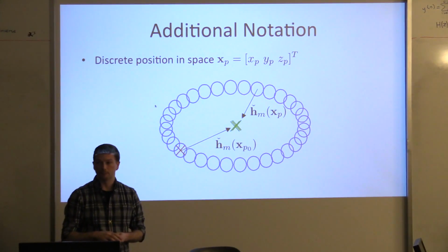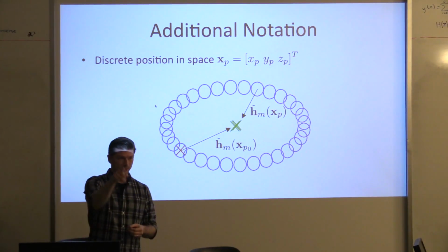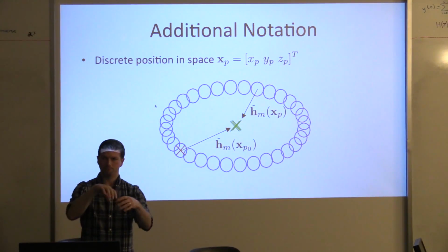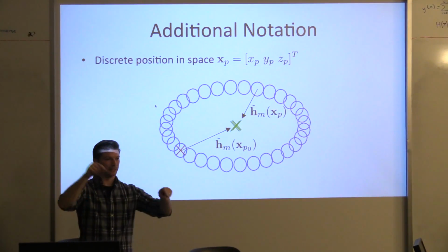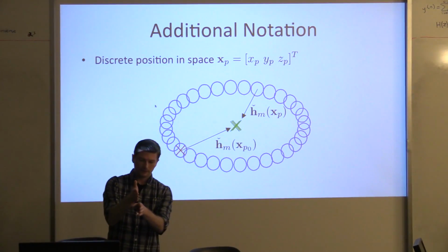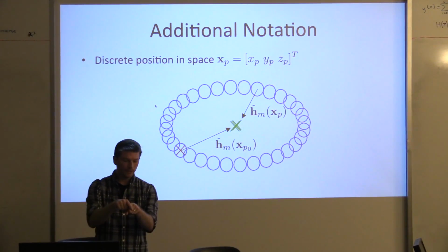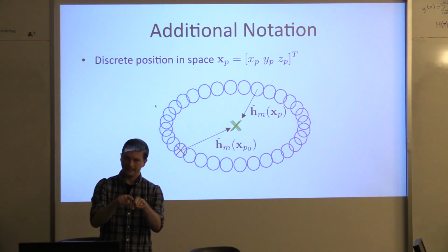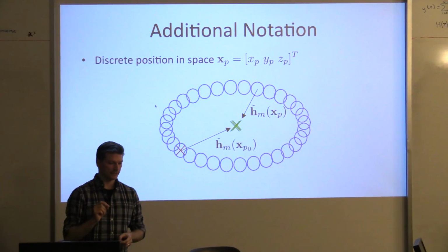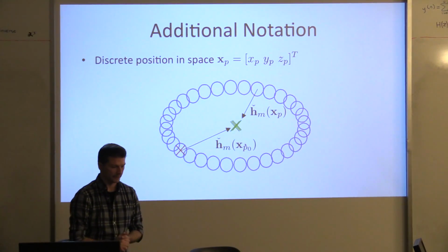So if we're going to design a practical beamformer, then often we want to know its response in several different positions in space. Now here I happen to have put it in a circle. You could put this on a sphere, or you could sample it at several different points, but just for simplicity, we've got it on a circle. So we've turned this into P different points. We've split it up. The x underscore p is the pth position. P0 is what I denote as the look direction. So P0 is what occurs here.